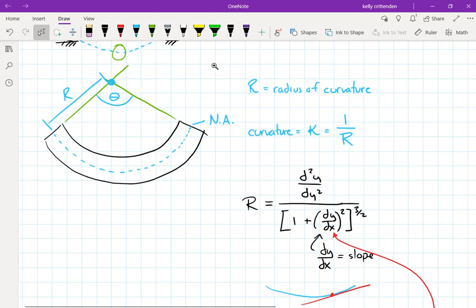In particular, strain is interesting at this point because strain is related to changes in length, and I know the length of the neutral axis. So the length of the neutral axis from this drawing, again really exaggerated, would equal, it's an arc length, so it would equal this radius of curvature times theta. Theta's in radians, and that's just an arc length, is all that is. And so that's the arc length of the blue dotted line.